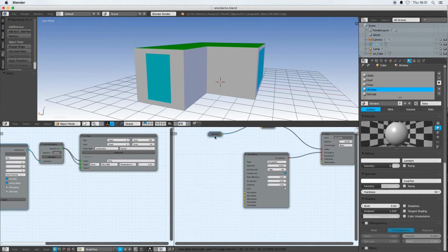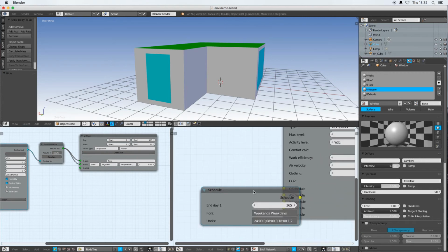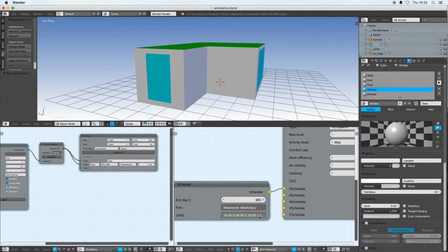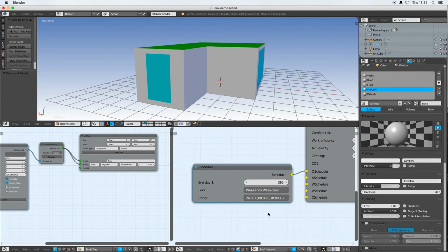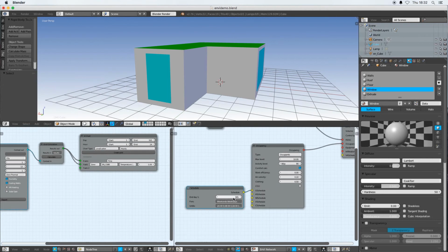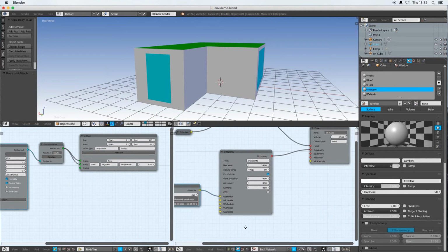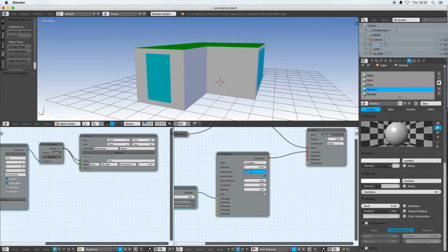In a way, because the occupancy schedule is going to be similar to the heating schedule, I can just copy this schedule node, bring that to the occupancy schedule node, and I can say, yes, actually that's perfectly fine as it is. So whereas 1 and 0 were turning on and off the heating system before, 1 and 0 now is specifying 0 people and 10 people. So that runs in accordance with our heating system, or at least I'm going to keep it so here. So we can set the activity level, watts per person. So 90 is a fine default for a commercial environment.